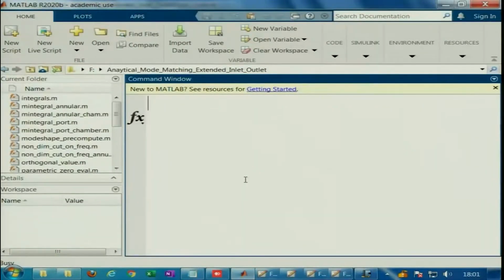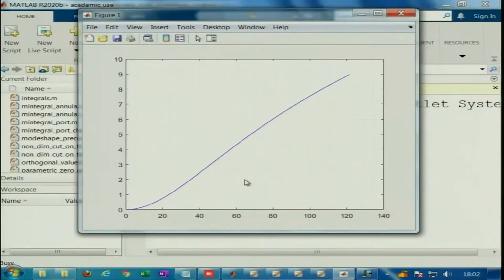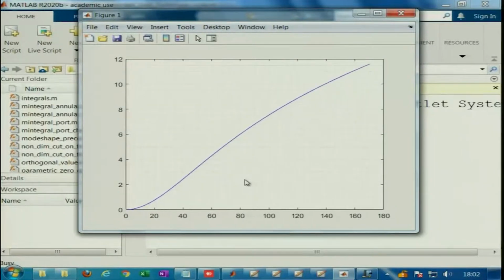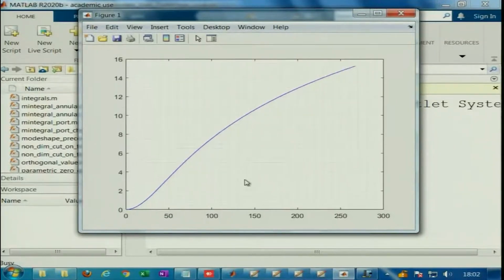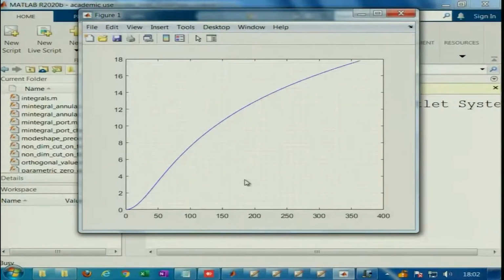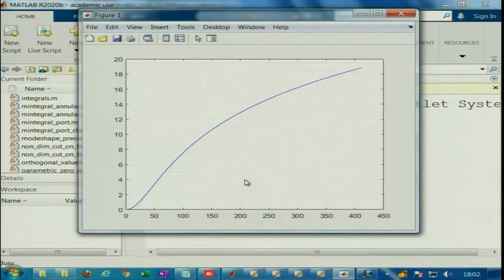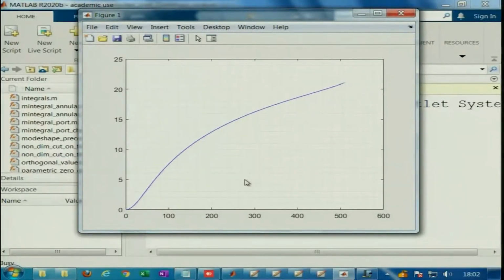Let us see if we are able to tune it. Clearly, one thing that we immediately figured out is 15.75 mm versus 11.72. So, roughly there is a 4 mm difference in the maximum or extreme thickness that we usually encounter in engineering applications. Especially if you have a larger expansion ratio, 5 or 6, the inlet diameter can be 50 mm while the chamber diameter can be 250 mm or 220 mm or something like that. Then you will have even more effect of wall thickness, although I am not going to show you those simulations because of lack of time.